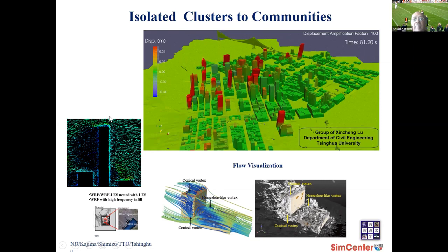And here is one example. We did the model part of the city of Houston after a windstorm while investigating the glass damage. And here are some of the flow patterns which help us to understand what was happening in the street canyon, which was corroborated with the flow visualizations. And later we did pressure measurements on the building to see what really was happening in that particular case.